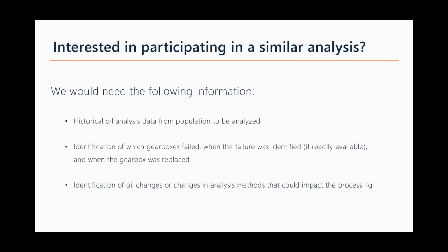Obviously, the oil analysis data itself, along with a listing of what gearboxes failed, when they failed, and when they were actually replaced, and identification of any oil changes or other maintenance activities that took place on these turbines that may impact the results of our processing. Ultimately, we'll go through and slice and dice the data in as many different ways as we feel necessary to either identify a correlation or prove that there isn't one, and share those results back with you.